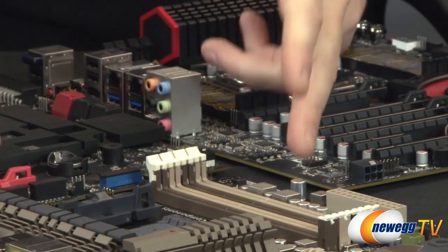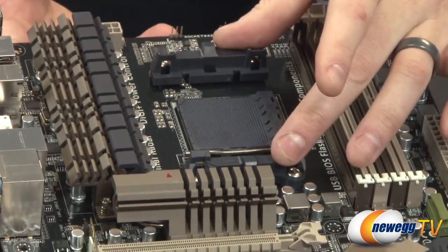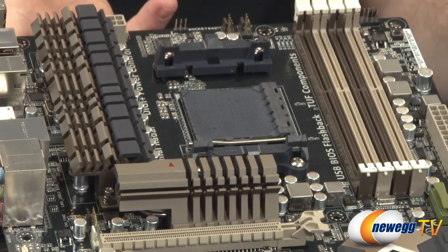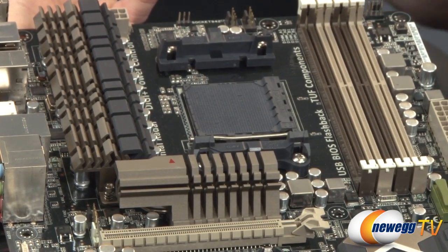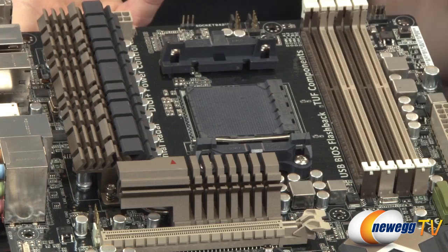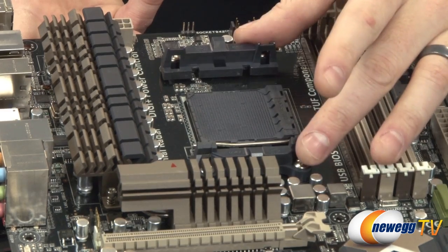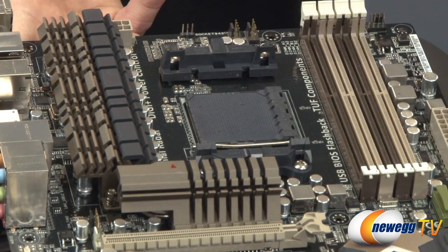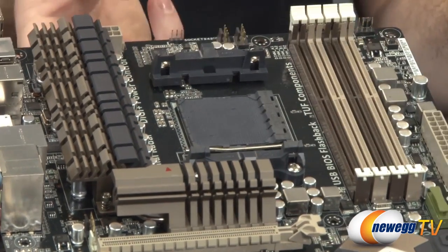Fortunately, at this point, there's been a lot of standardization. So for AMD, for example, and I got one of their boards again right here, their little saber-toothed, AMD has been using the same cooler mounting system for a long time, which is a godsend if you have a favorite cooler that's even 5 or 6 years old, because if you have a good working cooler, clean the dust off of it, it's going to keep working, chances are. So that's a very nice thing for AMD, whether you're talking about the FM1 or the FM2 sockets, or the AM sockets, AM2, AM2+, AM3, and AM3+, which they've been doing on their mainstream platform for quite some time. They have a standard mounting system here, so if you're going to go with what is known as an aftermarket CPU cooler, you can drop it right in and it will install correctly.